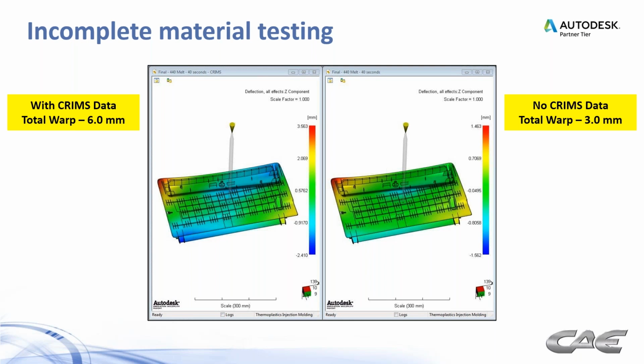And after they started molding parts, they noticed that the warpage was actually much higher than that. So by that time, GM had started their materials database, and that material became available, and we reran it, and it actually predicts 6 millimeters, which was more in line with what they were seeing at the press. So the cavity half of the mold was scrapped, new manifold built. We ended up having three gate locations, and we're able to flatten that part out. But at the cost of time and money. So it's really important to have good material data across the board for any analysis, and everybody should be insisting on that.